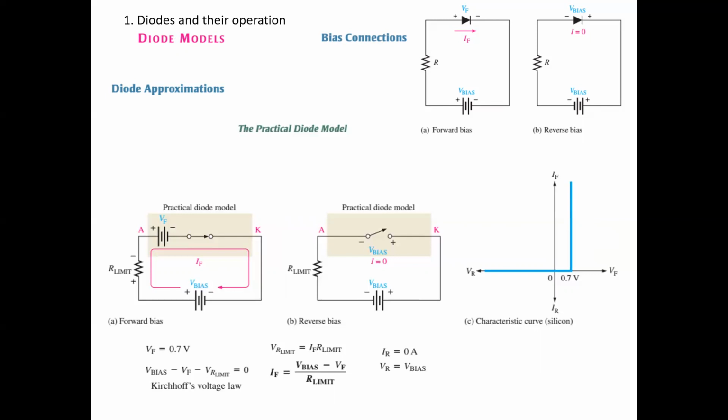But a practical diode works a bit differently from that. We have this forward bias voltage of 0.7. When we exceed that, only then does it conduct. So this figure indicates the forward bias voltage. These are some equivalent circuits. If you look at this circuit, you can see until we exceed this voltage, it is not conducting. So now we can represent the forward bias voltage like this.